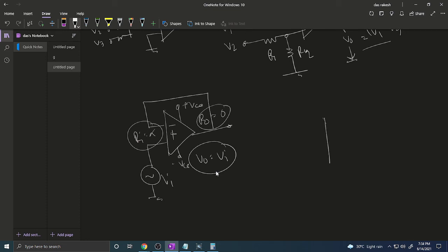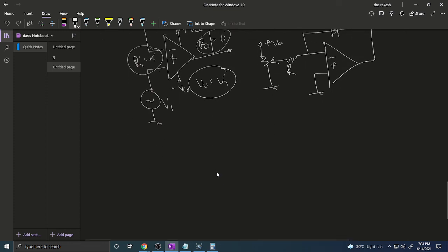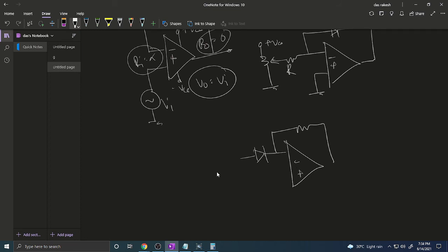And next, another circuit is the logarithmic amplifier. There are resistances and a diode present, and a potentiometer is connected, as we already showed how a potentiometer is connected in Proteus. And these are anti-log amplifiers. In the previous theoretical lecture, we discussed these different types of amplifier operations using the operational amplifier. Basically the operational amplifier is an analog computation device. So using this circuit, we can do analog computation of the input voltage present at the output. Now this circuit can also be implemented in the Proteus environment.